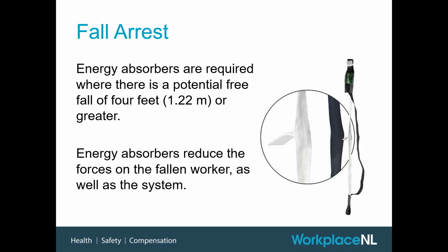Now, I'm not going to get into all the detail of exactly what I mean by free fall, but generally speaking, if you are in a situation where you're going to be falling, you need an energy absorber included in your system. However, if you're using your system for restraint purposes, these would not be required because you're not going to fall. Again, if the system is set up correctly, there should be no potential for your worker to fall. They effectively are on a tether, and that's the purpose of it, is just to prevent them from moving. So these are an important system to consider if you need fall arrest.